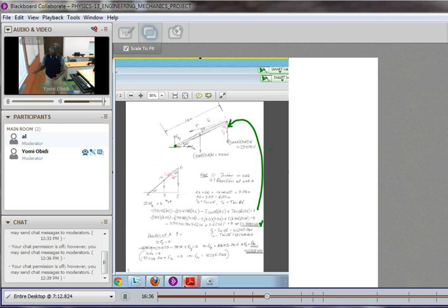If we then use another principle of equilibrium, summation of forces, you can do summation of forces in the Y direction or summation of forces in the X direction. Either of them would work. I've done both, and I just put this in parentheses. It's actually the summation of forces in the Y direction that has been used to get this answer, but it doesn't matter. That's just an option for you. When we sum the forces in the Y direction, the summation is 0.